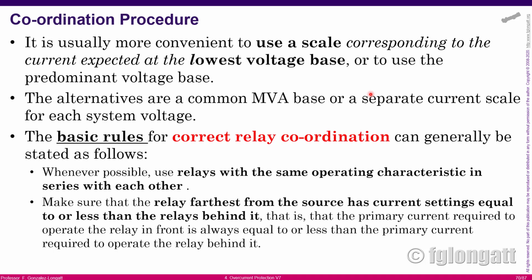Again, my protection guys will say this is not a good practice. Well, if you are working in distribution feeders and calculating only phase protections, I mean protections against three-phase short circuits, it's not a rule, it's a practice that could be useful, and probably 99.9 times it will work.